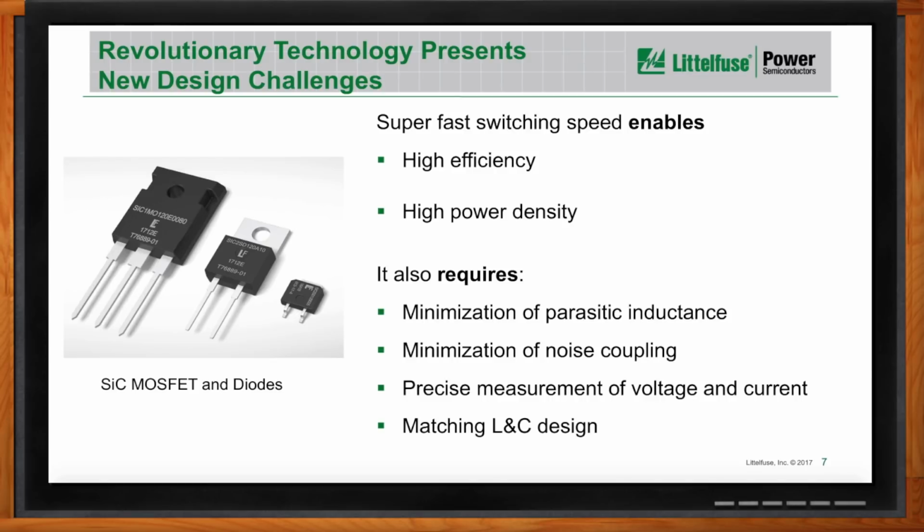So that's where, for example, you need to minimize the parasitic inductance in your whole power circuit, and also minimize any noise coupling, and it also needs some precise measurement of all your voltage and current to make sure that you can get the correct information for your control.